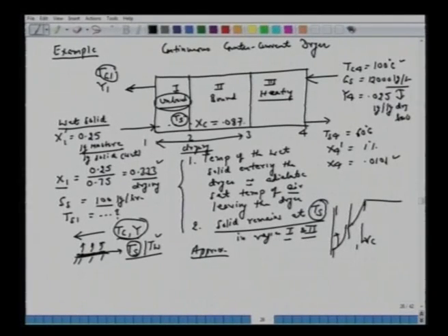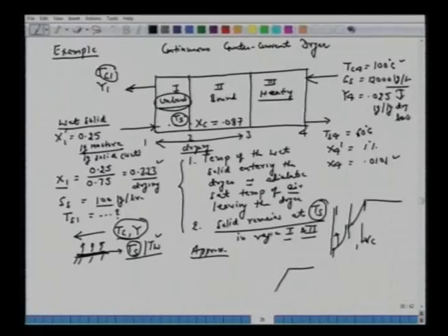All right. So again, notice here, if you recall, we said that in this drying, this critical moisture content or equilibrium moisture content, they have to come from this characteristic curve. In other words, one has to do this experiment. You have to take the same solids and simulate in the lab, more or less with the same Reynolds number of the gas fluids, the same temperature, or the solid surfaces to which it's exposed in the laboratory. So one has to establish this drying curve, which we have been using quite rigorously in the first lecture on this topic. All right.